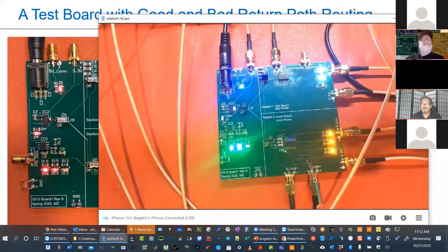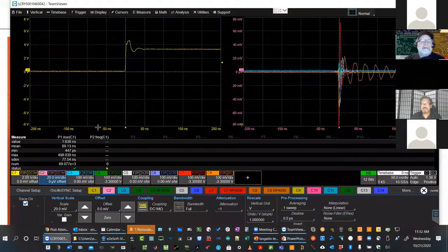So let me show you my scope. And it's a trigger. It's just going to turn on. It's got like a 500 hertz clock or so. And here we are. Here is the measured voltage in channel 1, which is the trigger output. And you can see it's kind of a funny signal. It's 3.3 volts coming out eventually, but it's got a little bit of ringing in here.